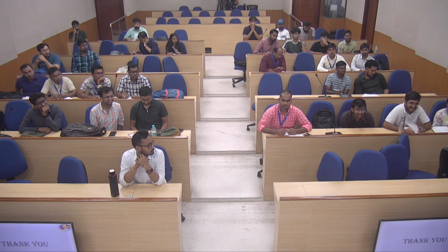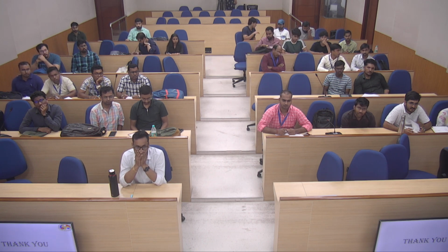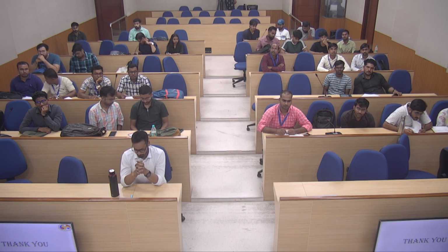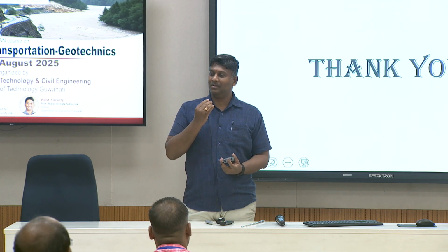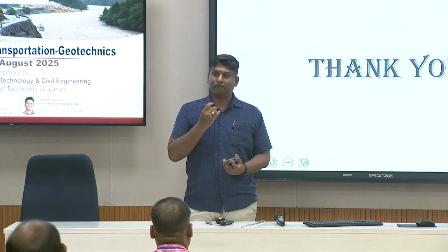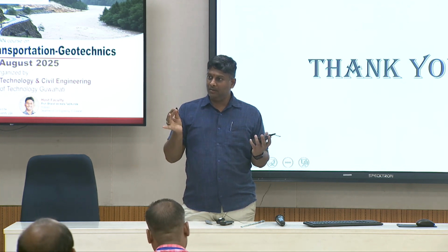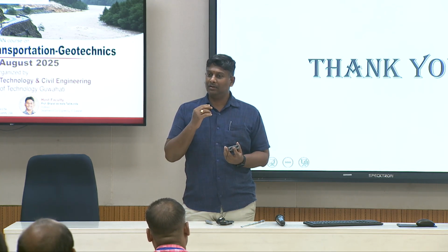What is it? Suction measurement. Same issues. Same issues. So it takes a very long time to establish the equilibrium. Papers are there, published by Professor Tripathi et al. I guess in the Indian Geotechnical Journal, and later on we have some works also. Yeah. So the measuring range is quite high. Almost it goes to several hundreds of MPa, but then it takes a very long time.